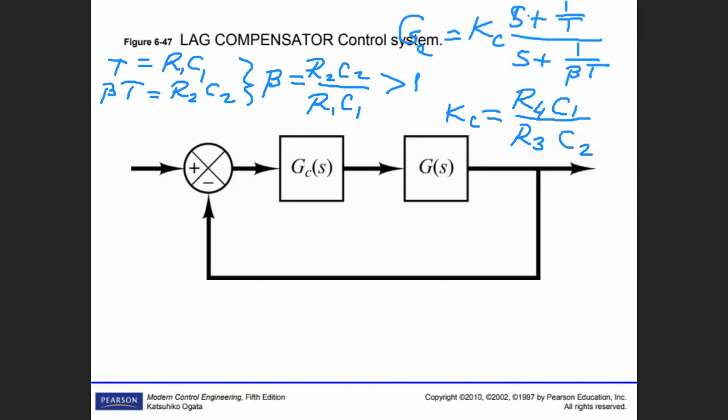To avoid a big change in the root locus, the angle contribution of the lag network should be limited to small amounts, say less than 5 degrees. So the lag angle changes should be lower than 5 degrees.